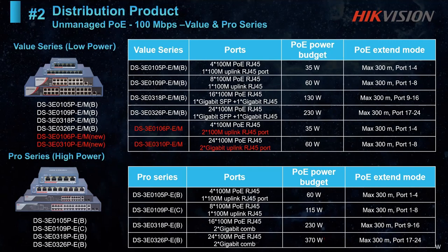And Varuna, one more thing to mention, the camera power requirement is actually mentioned on the datasheet. Normally a standard PoE camera will consume around 2.5 watts, as I remember. So when you are planning your CCTV system with IP technology and deciding on your switches, it's very critical that you have a clear understanding of the PoE power budget of your switch.